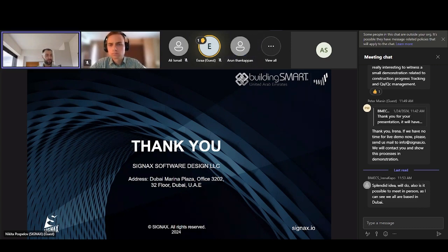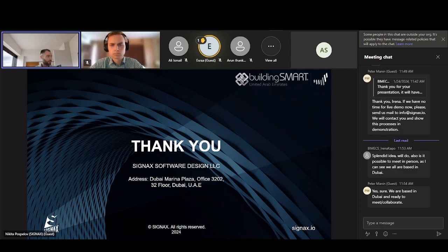Okay, thank you for your question, Mr. Arun. So regarding the invoice export, we were tracking progress on the federated, design-stage federated BIM models in Navisworks using SIGNAX tools. Using SIGNAX tools, we are marking elements as completed during the construction stage. In everyday work, field engineers responsible for tracking progress for each discipline were marking, at the end of the day, elements as completed using automated source set creation, or just manually selecting the elements or group of elements as completed.